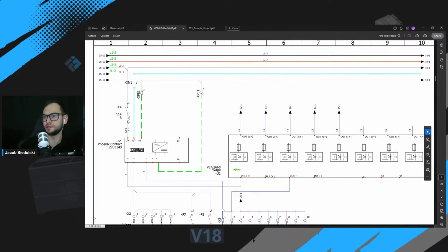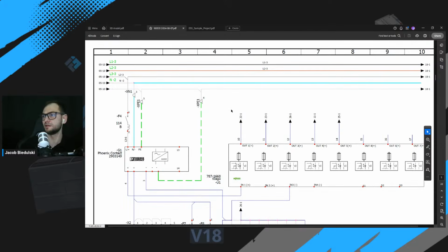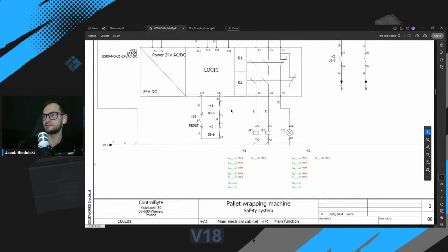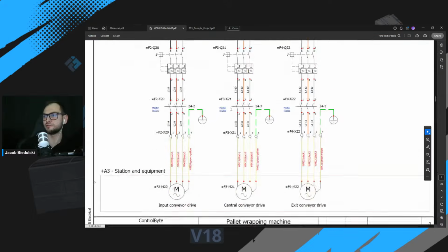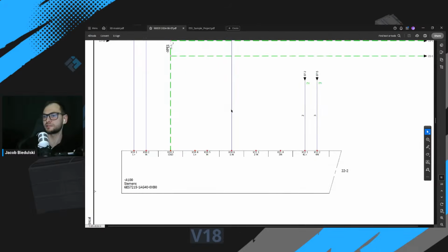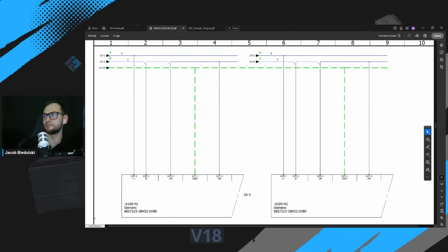And then every device is connected to those lines. Here you can find, for example, 3 phases, a neutral, potential earth lines. But in the same manner, you will also find, for example, 24 volts power supply lines for PLCs and low voltage equipment.